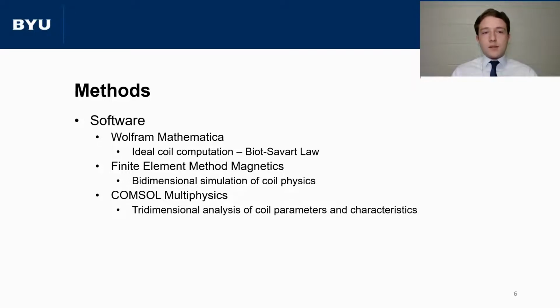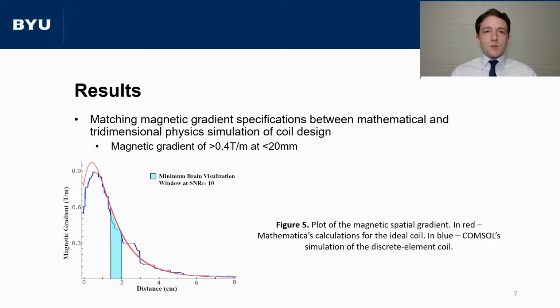Since the coil is to be driven by a 500 kHz sine wave, we opted to use Litz wire that matches the skin depth of copper at that frequency and reduces the skin effect caused by the high frequency current in the wire. This optimized motion encoding coil was then placed in an LC resonant series circuit, which was then used to effectively cancel the imaginary resistance of the coil while creating a pure 500 kHz sine wave.